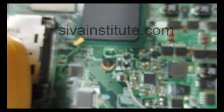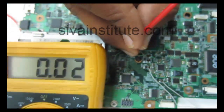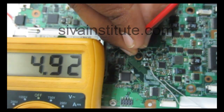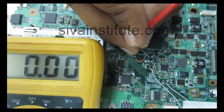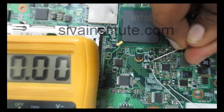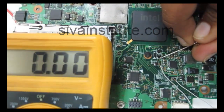We will see the voltage without the SPI command. First, gate voltage 4.9 volts, drain voltage 0. Source voltage 0. Source is already grounded.